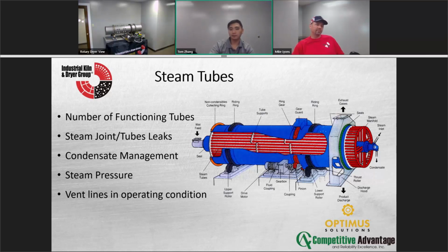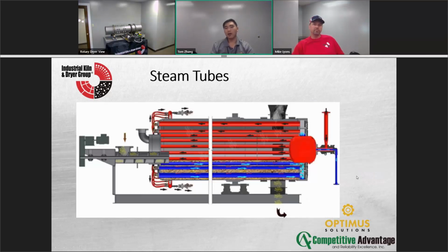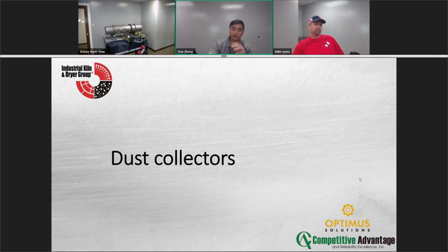Yes, absolutely. There's another view. Hot steam goes towards the discharge, so the left is discharge, the right is the feed. And then there's a siphoning effect as it goes through to get the water coming back, and then the water has to exchange out. So it's effectively a giant heat exchanger. Every one of these units is a heat exchanger. Steam tubes are always unique in that sense.